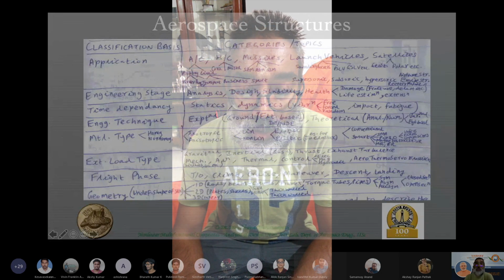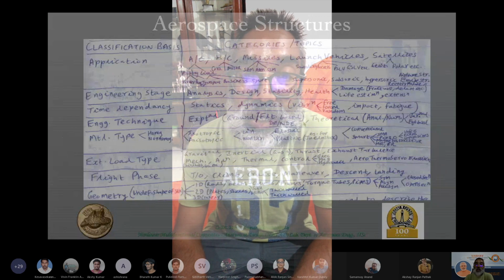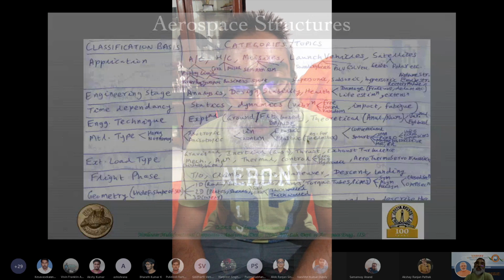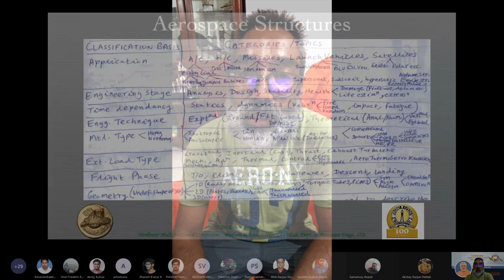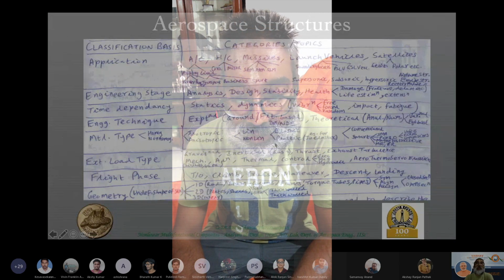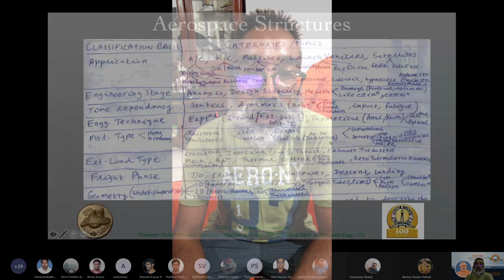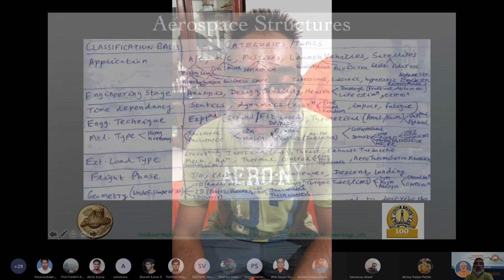Then coming to another classification of the materials which are used in an aircraft structure, some of them could be elastic, in the sense that when you remove the load, all of the deformations are removed as well, and it comes back to its original shape and size. Whereas in the case of a plastic material, there is certain permanent strain which remains in certain directions, which is a permanent deformation. And plastic is just an example of inelastic in general. So you could have various forms of inelastic materials.